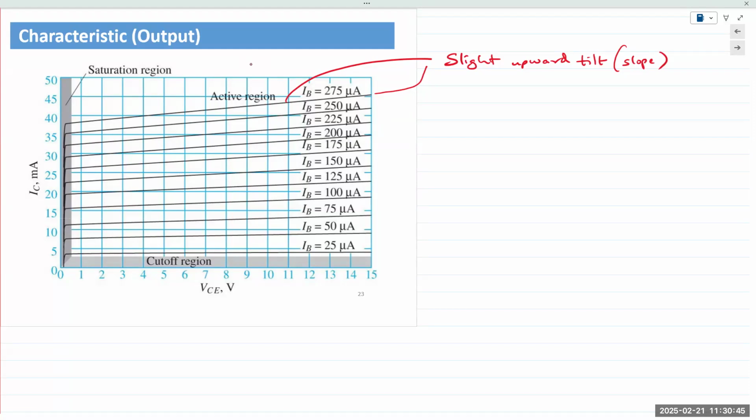We have done that for diodes, Zener diodes. So we'd apply KVL, obtain 2 points, draw the load line. And on this load line, we'd find a point somewhere near the center. And that would be our Q point.